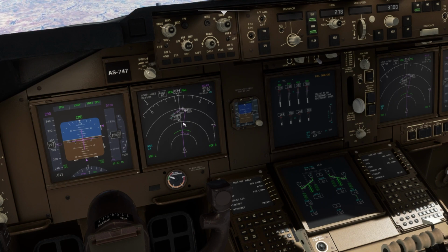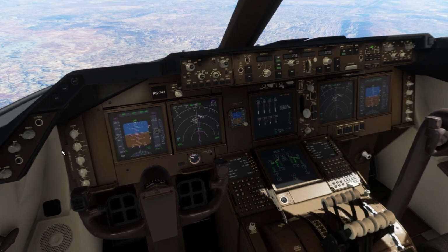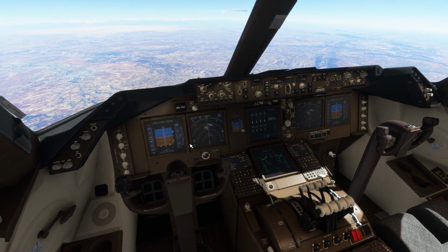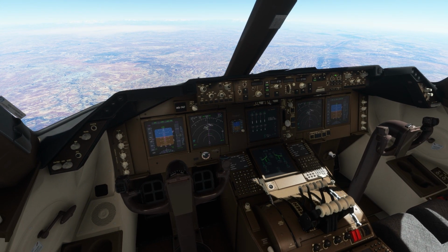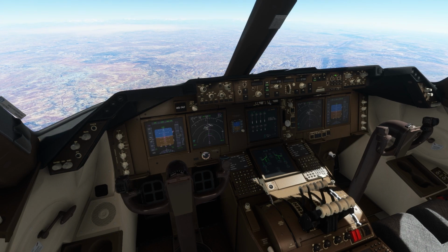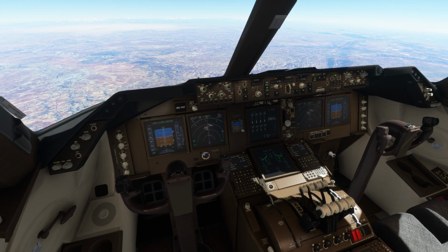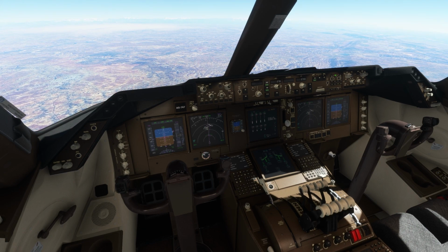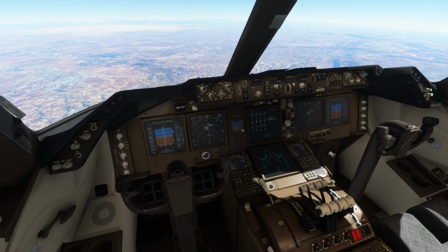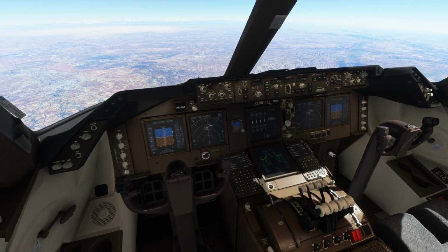As soon as the plane is below 10,000 feet, I will turn on the lights, and I will also start to extend the flaps, because flaps provide not only drag, which reduces the speed of the plane, but also provide additional lift at low speed. So with the flaps extended, you can go at a lower speed. But if your flaps are not extended and you try to go at a lower speed, the plane might stall.